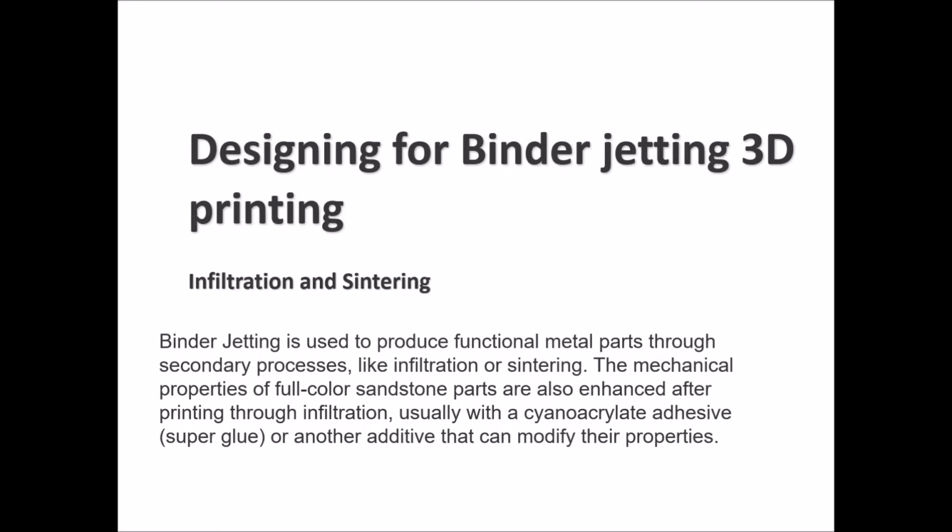We discussed that binder jetting can be used to produce functional metal parts by doing secondary processes. These secondary processes can involve something similar to infiltration or sintering. The mechanical properties for the full color sandstone parts can be enhanced after printing by using infiltration, and this can be done by adding a super glue material or adhesive to your printed parts, or even several other additive materials that you can use to modify the properties of the final printed part.